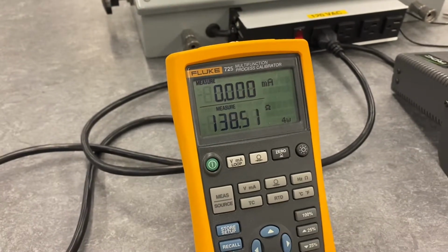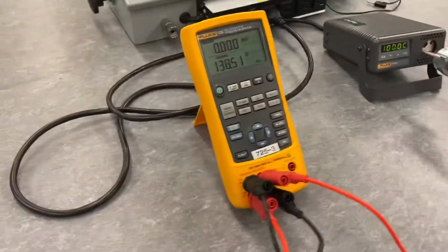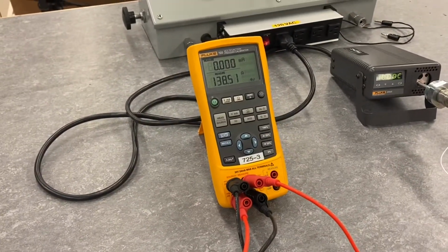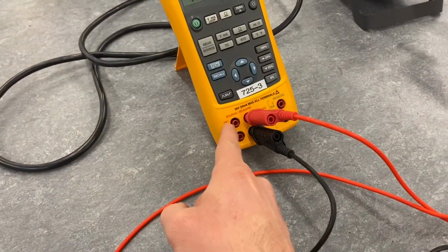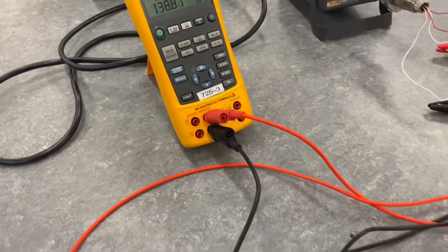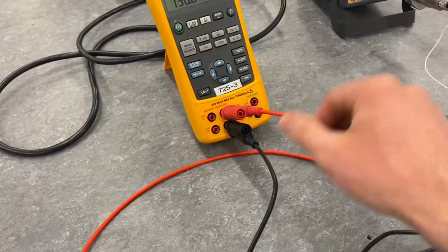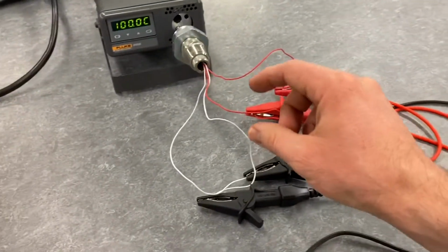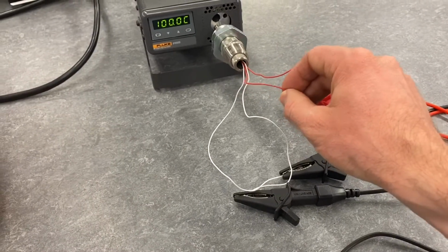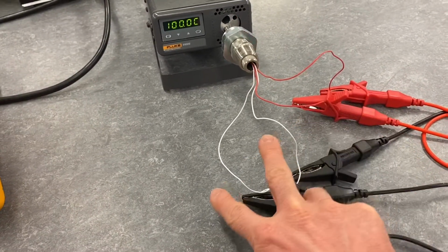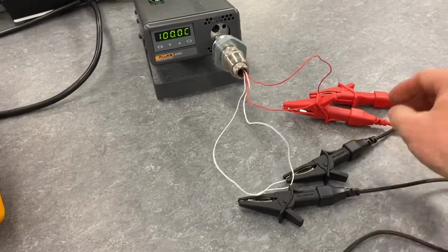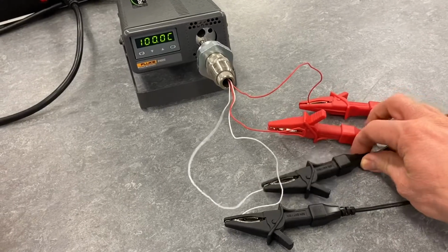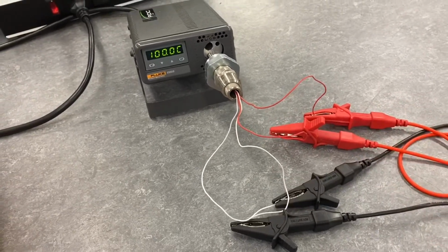Now, just to show you that our 4-wire measurement is more accurate here, by using all 4 wires, what I wanted to do is switch to the 2-wire configuration. All right, so to switch to the 2-wire configuration, I just had to unplug 2 of the wires here from the calibrator, and now we are only using 1 red lead and 1 black lead, one from one side of the resistor and one from the other side. These 2 white wires go to one side of the resistor, these 2 red wires go to the other side. So now we're just using 1 red and 1 white lead here.